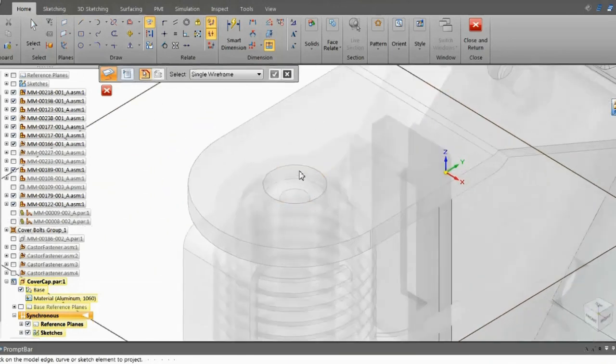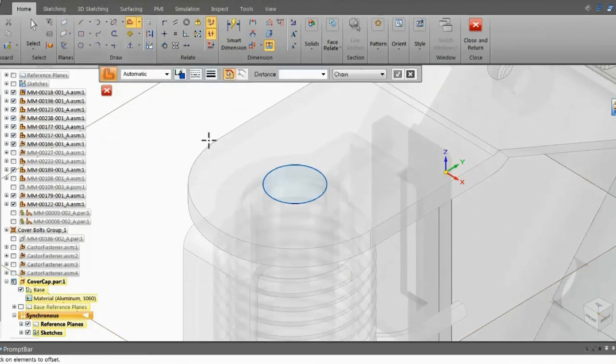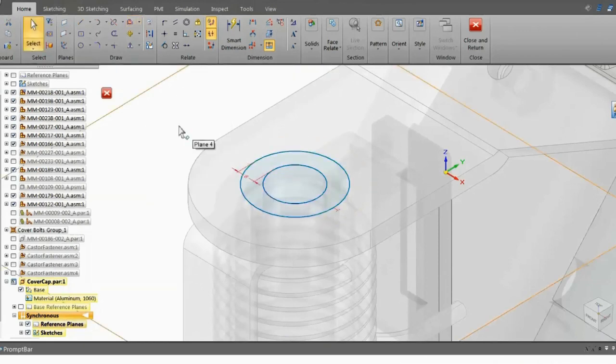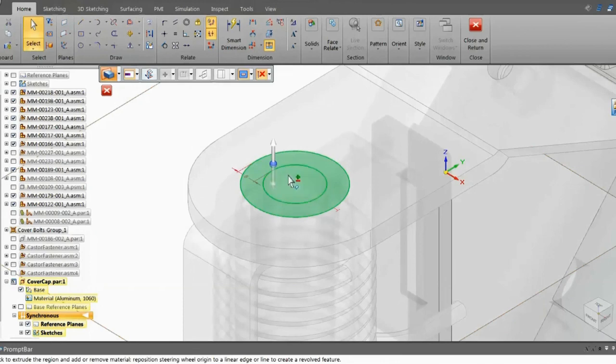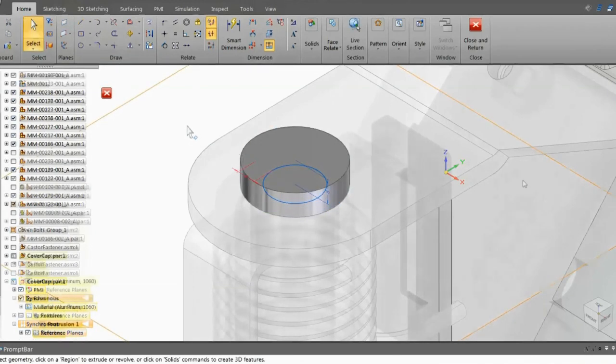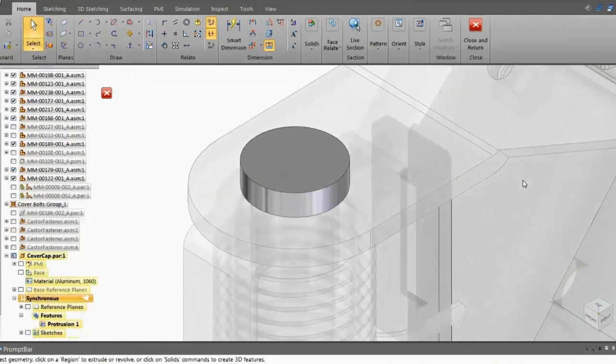design. The Project to Sketch command helps in creating new 2D geometry by referencing elements from the existing components of the main assembly. You can also use the Offset command to add more geometry without having to actually create new 2D entities explicitly. This gives you regions which you can select to produce 3D objects for the new part.